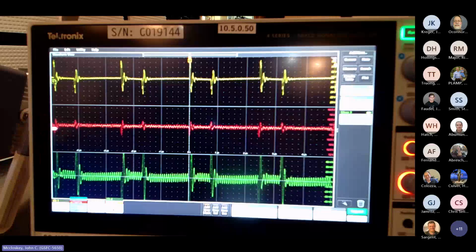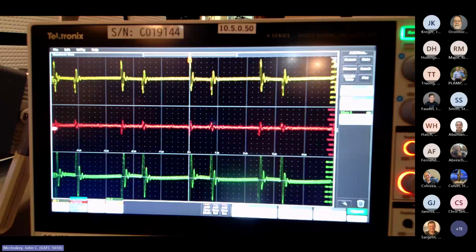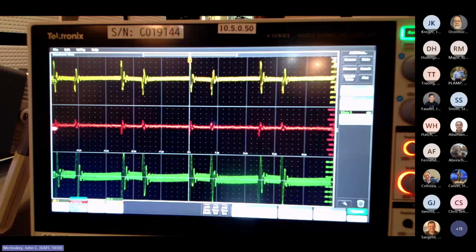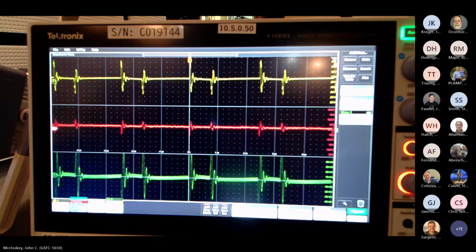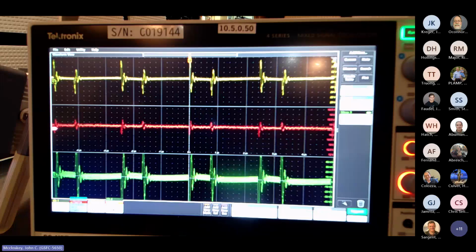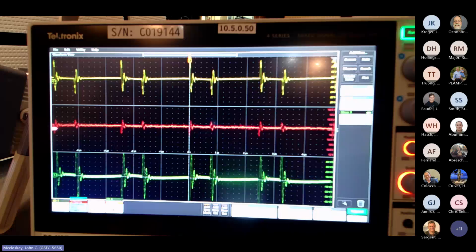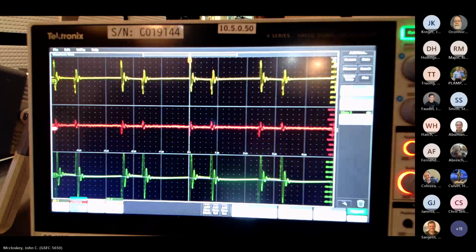Because that's really your ultimate figure of merit: what is the differential potential coming out of your power converter? You're doing common mode injection here, but how much of that common mode is converting into a differential mode signal that's getting onto your output potential? If you've got that much common mode, it's not good either, but that comes down to grounding and filtering and stuff like that. But that gets into design, which is the subject for another discussion. But that is basically what I have to show you.